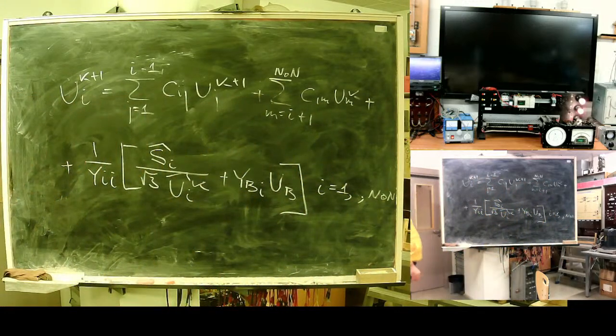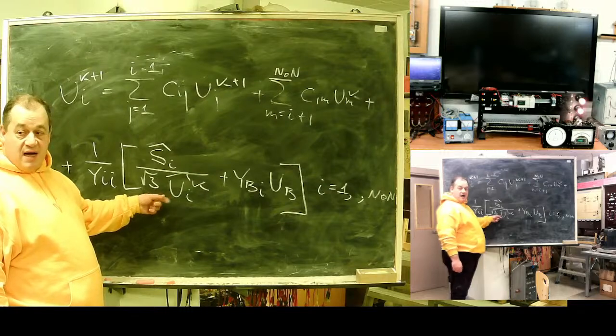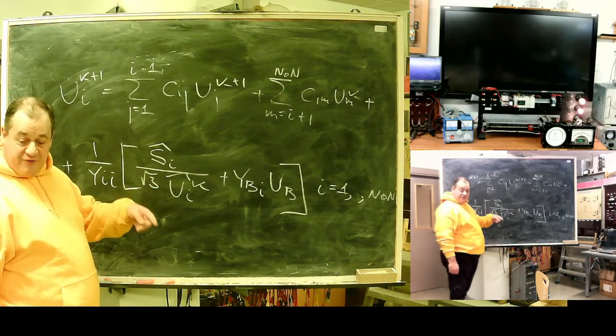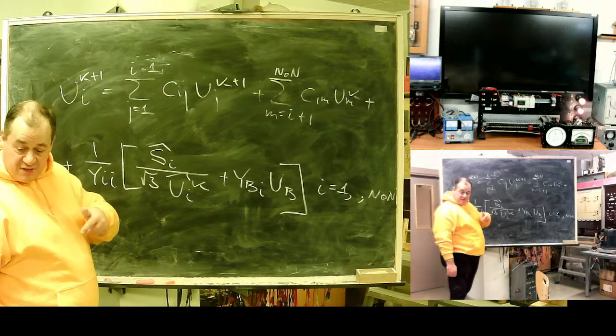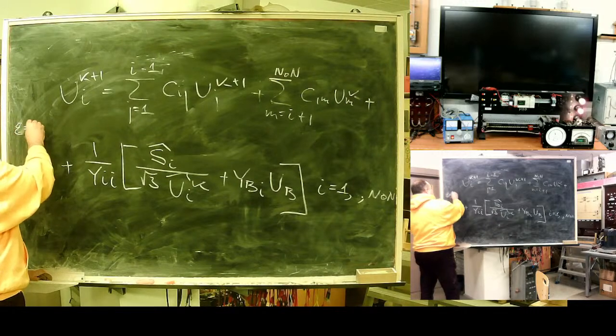Here I got a way to solve the problem of a nonlinear network with an upgrade of the Seidel technique. At each step I will recalculate currents. My current sources will have the previous step voltage as control value. No problem with precision.